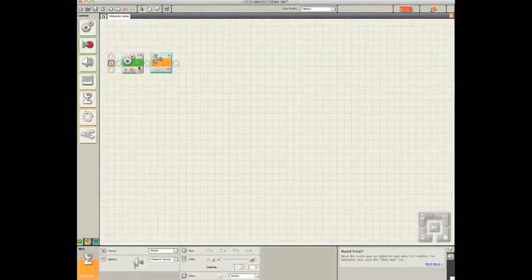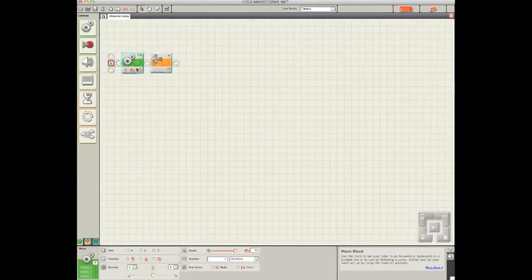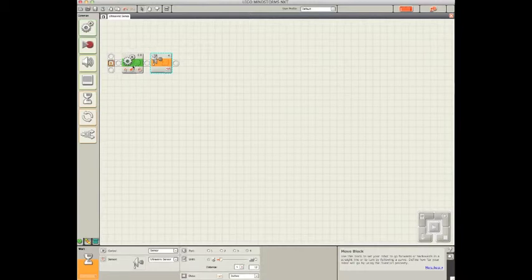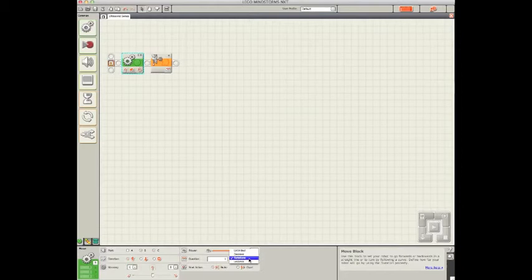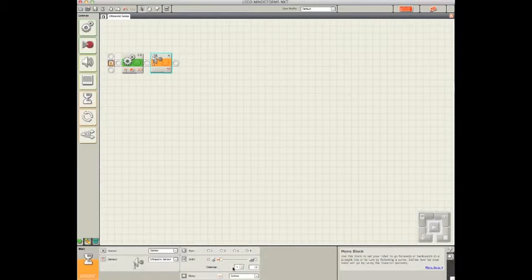And let's finish this example. So you want to go forward. Again, for the wait block, always remember that the thing before it needs to be unlimited, because you're going however much you need it to go until it senses, in this case, until the object is less than 12 inches away.